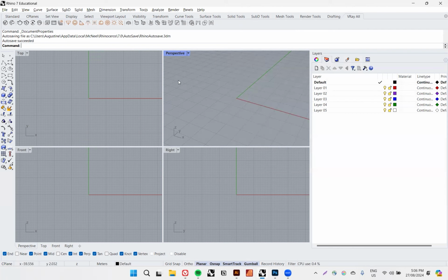Next, how do we actually use Rhino? Down here, we've got a bunch of little pointer stuff. First you have your 4 viewpoints: top view, front view, right view, and I think that's pretty self-explanatory. Afterwards you have this set here, which tells you how it's going to select an object. It's a little complicated, but I hope that as we go along, you get the gist.